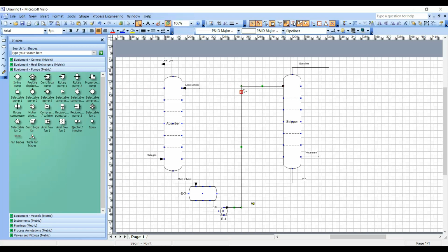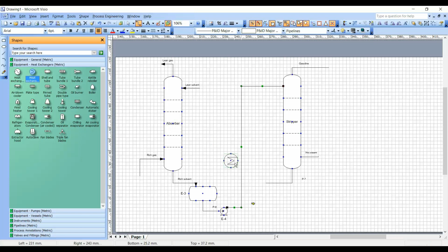But the point here is that the things that you are putting into the column have to be hot, so it's easier for the gas to come out of it. So one thing people would do is to do heat exchanging between that hot stream and that cold stream. And this will be something that we can do here from the heat exchangers. You can take this thing here. So first, because it comes really hot, you can just cool it a little bit, or just use this heat exchanger.